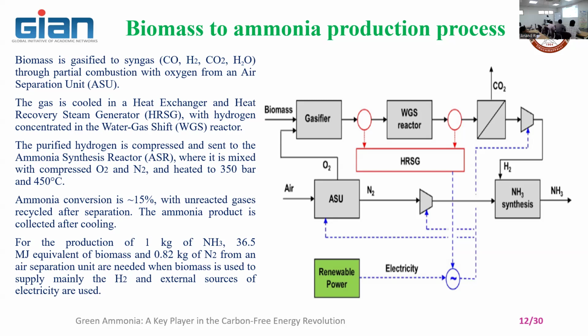Normally, this is a good system actually, because if you supply air into the gasifier, the formation of oxides of nitrogen is also there. If you separate the nitrogen and oxygen in the air handling system itself, and supply only oxygen, there is no possibility of oxides of nitrogen coming out from the gasifier.